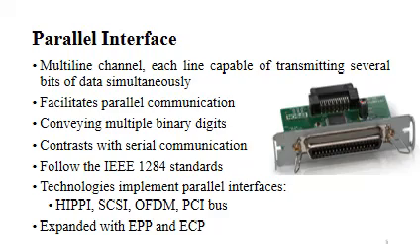Today, parallel ports follow the IEEE 1284 standard defined in the early 1990s. It specifies the traditional 25-pin D connector and Centronics connector as well as a new 36-conductor connector that is smaller than the Centronics connector. The connector has better electrical and physical properties.